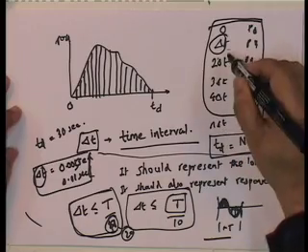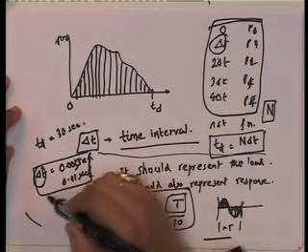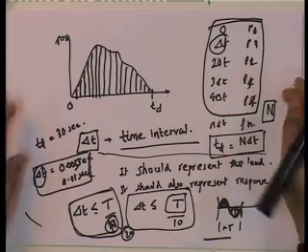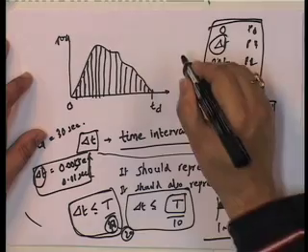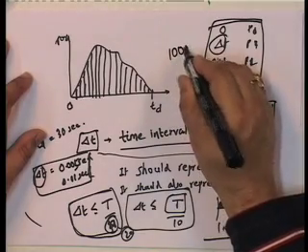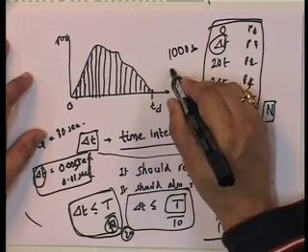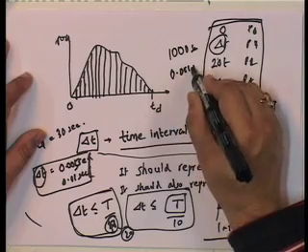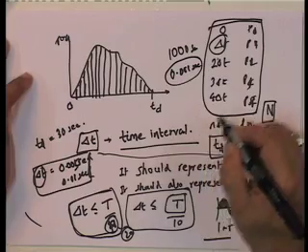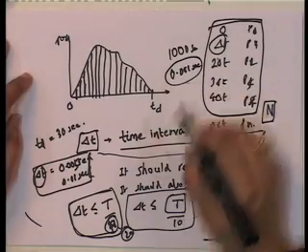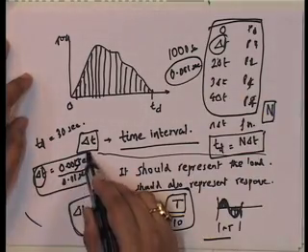Now, if we digitize, how should we get this? Well, there are ways and means of doing it. Sometimes it is called downsampling. For example, let us say you are doing it at 1000 samples per second. So, you are picking up at 0.001 second, but you do not want to do the analysis at that, you want to do analysis at this.